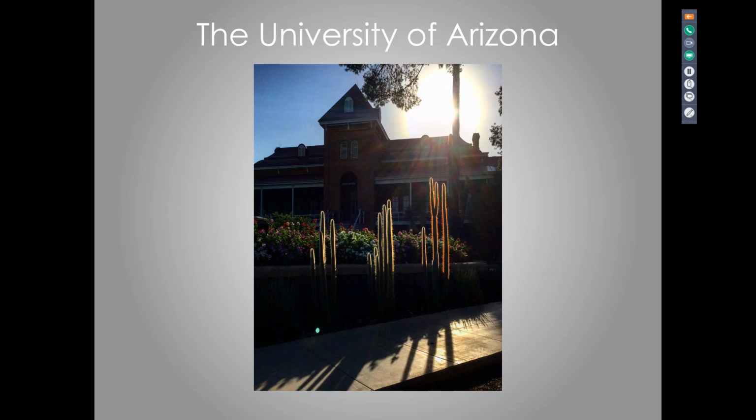Well, that consists of sending guys down into the vaults and the tunnels, documenting existing conditions, photographing. We've built a BIM model in some cases. We've taken video, really getting into the weeds, the nuts and bolts of it, identifying what the problems are, and assessing what the individual discrete costs are to replace, repair, renew. It's really a hands-on kind of effort.